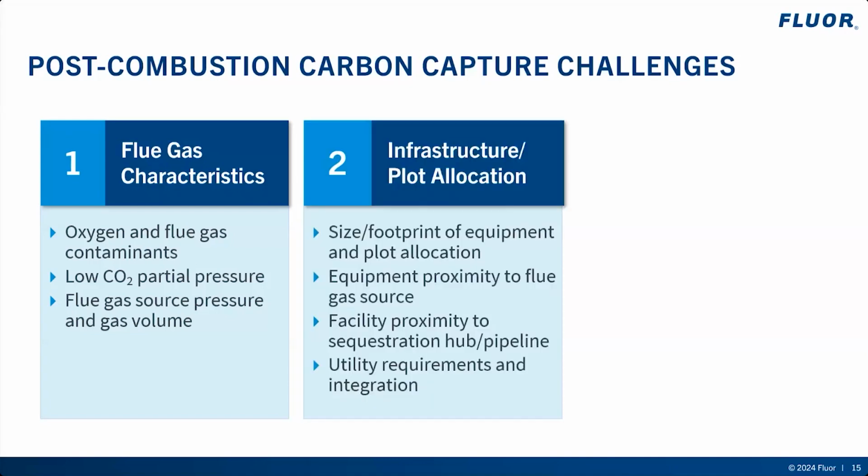Second is consideration of the facility layout and identifying where the new carbon capture plant will be located. The carbon capture plant requires a relatively large footprint associated with the large flue gas handling equipment and significant utility cooling infrastructure. Generally, the flue gas handling equipment should be located in close proximity to the emission source to minimize the electrical load demand of the flue gas blower and to minimize the flue gas duct routing requirement.